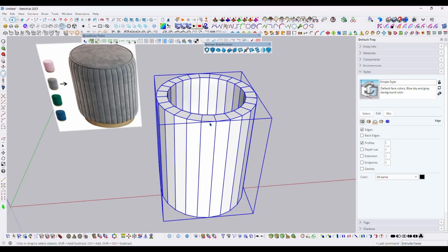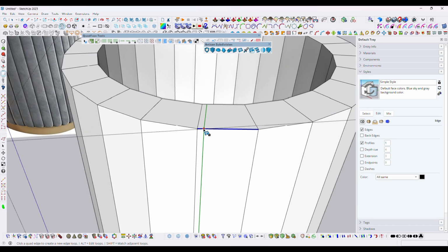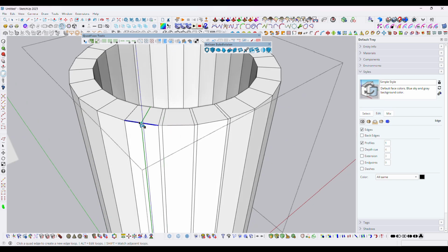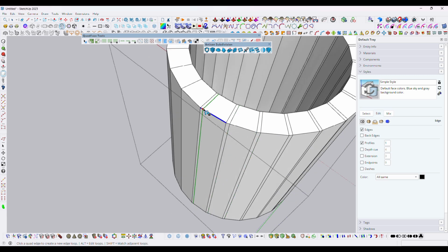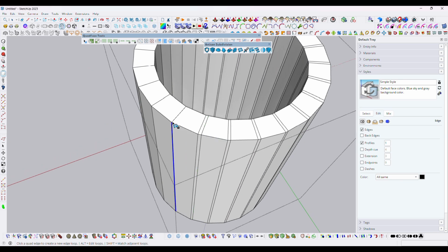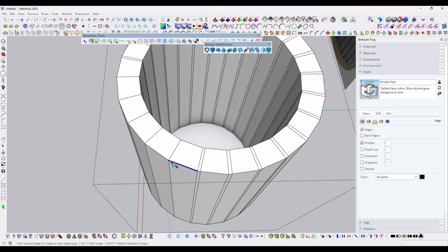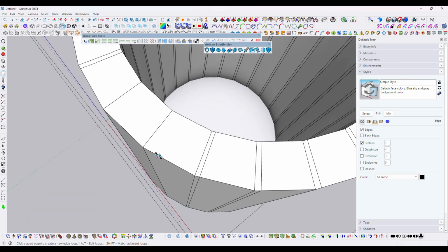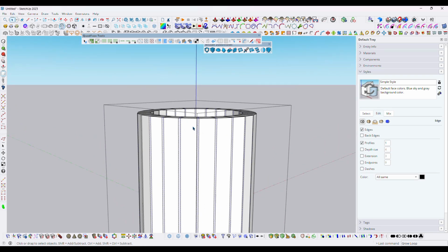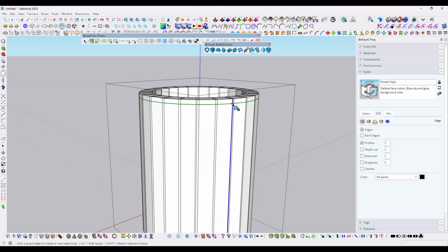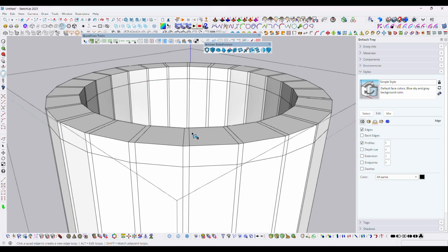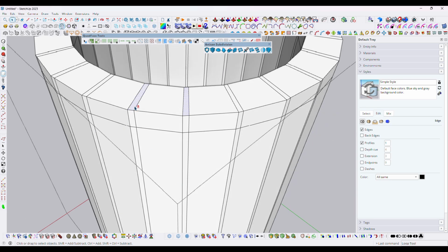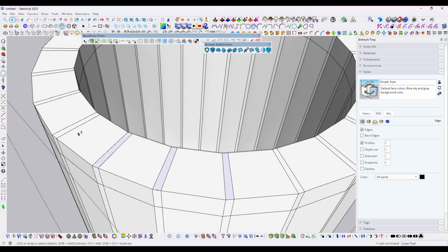Now guys, here you have to go inside this group and select the loop cut option. So you have to just click at a certain distance to create a loop like that. On every segment, just click one by one to create a loop cut. Now again click over the loop cut option and create a loop cut over here just like that, and inside this face also.